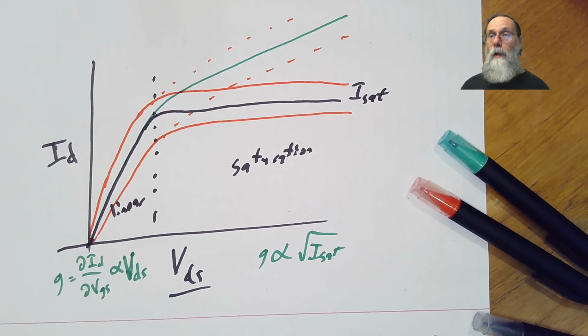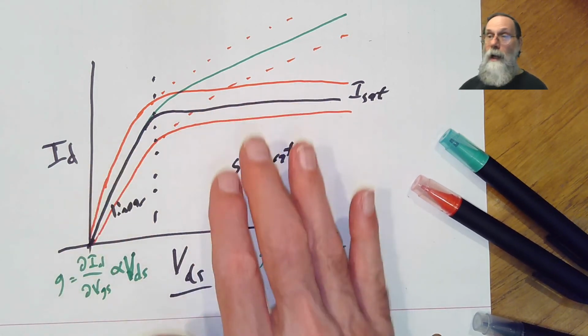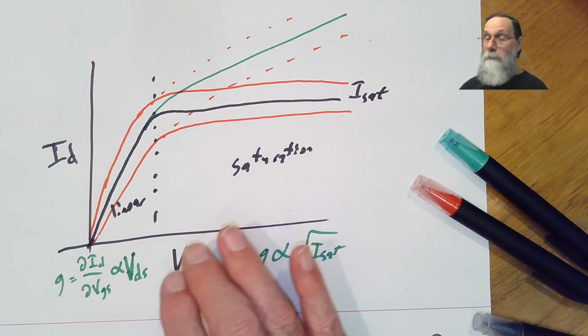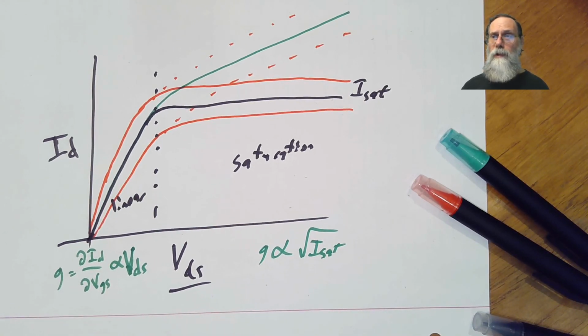What that means when you're using your microphone is that you need to put a voltage across the microphone enough to get a substantial current, and that's going to take you into the saturation region somewhere. So you have to make sure you've got enough bias voltage in your microphone to get you into saturation. And that's probably all you really need to know about the junction field effect transistors for what you're going to be doing with them in this class, because you're not going to be designing with the field effect transistor itself, just with the microphone that incorporates the field effect transistor.